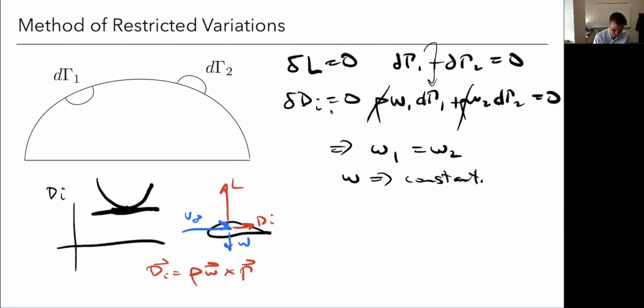And so the wing, imagine I've got this wing, right? And it produces, as we've seen, kind of these trailing vortices, a pair of counter-rotating vortices. So here I'm just drawing one of them on the right side of the wing. So if I now add this winglet here, right, you can see that that vortex is going to be pushing on that winglet. It's going to induce a velocity that's going sideways, right to left here on that winglet.